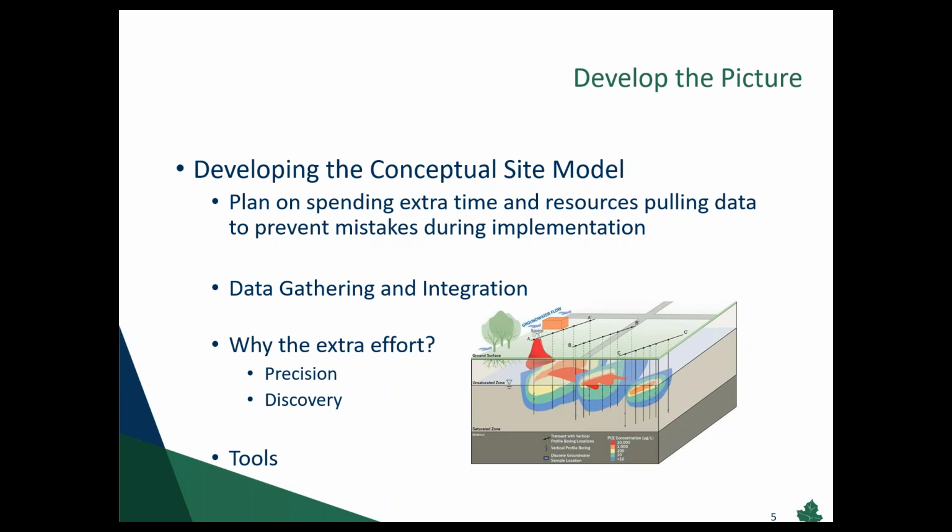I would imagine real-time probably costs more initially. It does. But time-wise, it's probably better on a lot of sites. Yeah, you can basically chase the plume. You'll see when you're out of it, and then you can come back and go a different direction, see if you're back into it, and just continue to chase it till you've got your contamination really well delineated.